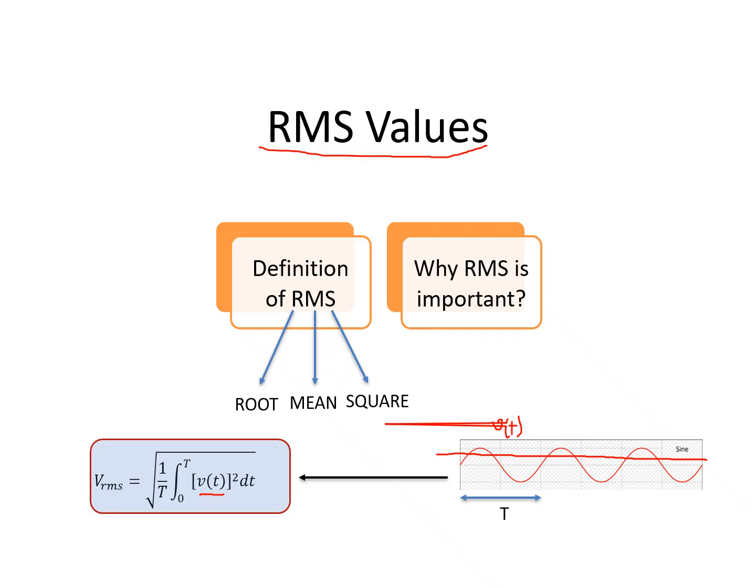So unlike instantaneous values that we have in DC circuits, the RMS value represents the equivalent DC value of a signal that would produce the same power. Moreover, all multimeters and measuring tools that measure AC signals operate based on the RMS value of the signal.